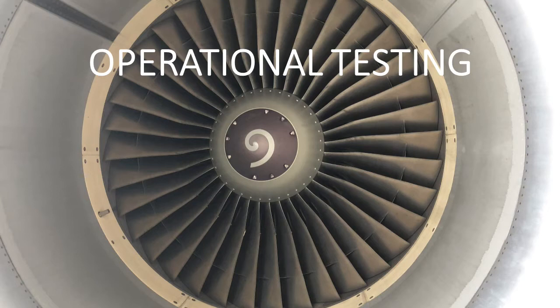There are slight differences that we see on display in the cockpit, and Rick can attest to that, and we can talk a little more about that later. But the operating pressure needs to be 3,000 psi. Okay, and this is just for the A320. When you start talking about the heavier aircraft, like the A350 or the A380, those pressures are going to change. Why? Because now you have a higher demand, because you have more mass with the aircraft.